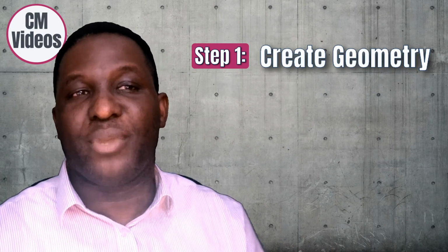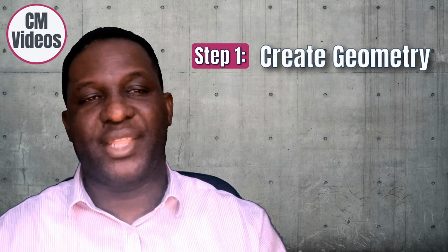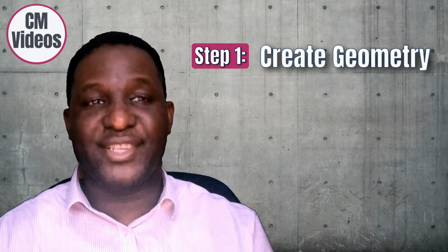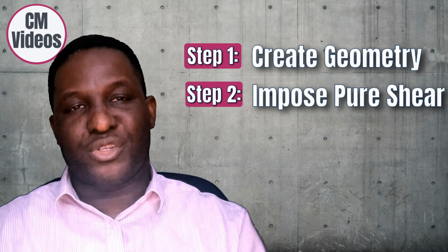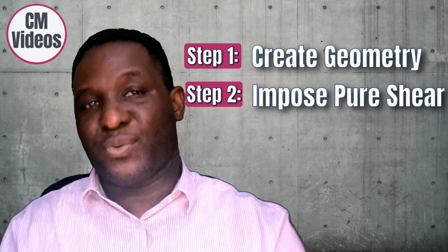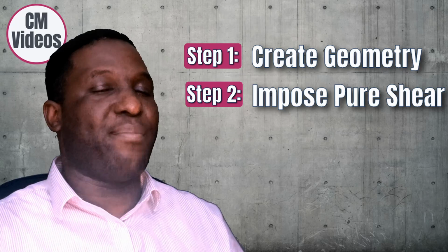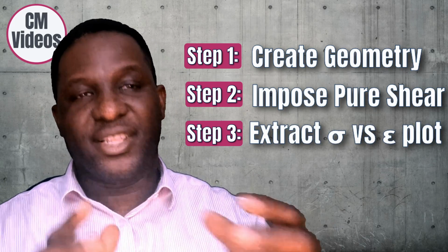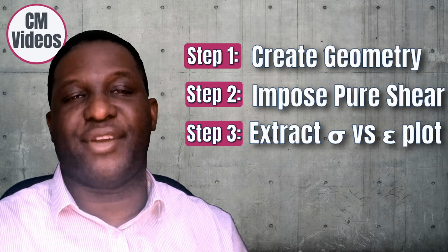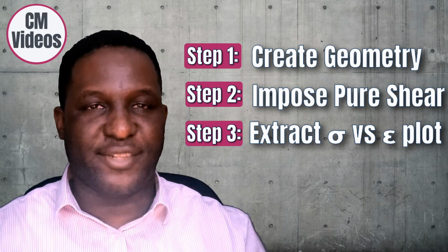So welcome to this video. There are 3 steps that you need to follow in order to apply this pure shear deformation on a syntactic foam. The first step is to create the geometry, which is the generation of the virtual domain. The second step is the nitty-gritty of the steps required for imposing the pure shear on the structure, and we're looking at this in terms of the XY, YZ, and ZX shear planes. And finally, the third step is how to extract the stress-strain data that will help you generate the effective properties of this material.